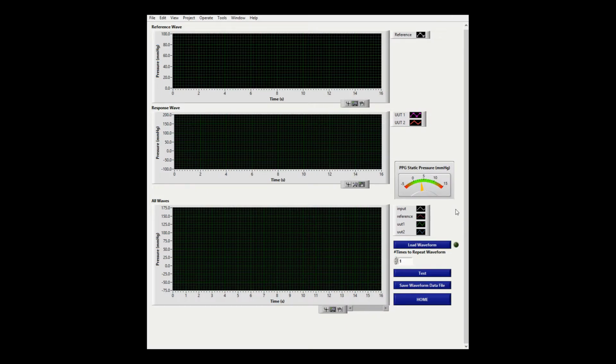After the Custom Waveform Response window appears, scroll to the bottom of the window and press Load Waveform. A new window appears. Choose the delimiter that the custom waveform uses. For a CSV file, this is typically a comma, or a tab represented by a \T. Choose an interpolation mode. Spline is generally good enough for most waveforms. For very long waveform files, interpolation may take a long time. In this case, use the linear interpolation option to reduce the interpolation time.